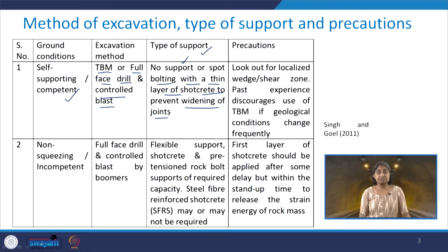One needs to exercise the precautions listed here: one has to look out for localized wedge or shear zones. The past experience discourages use of TBM if the geological conditions change frequently.